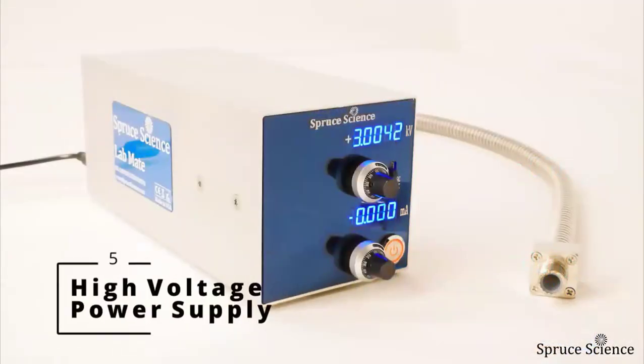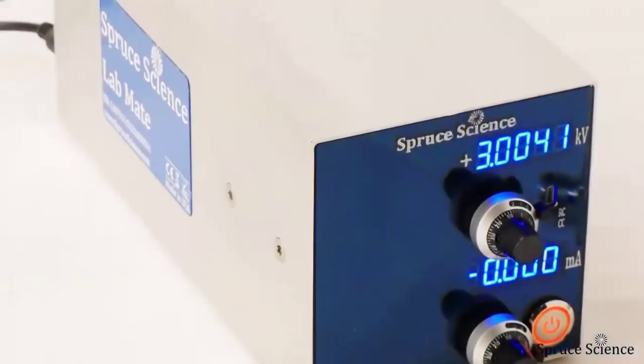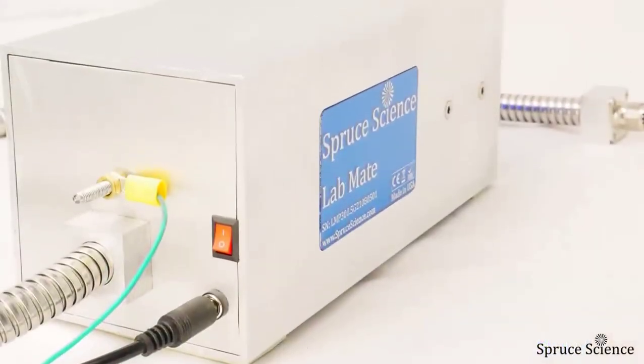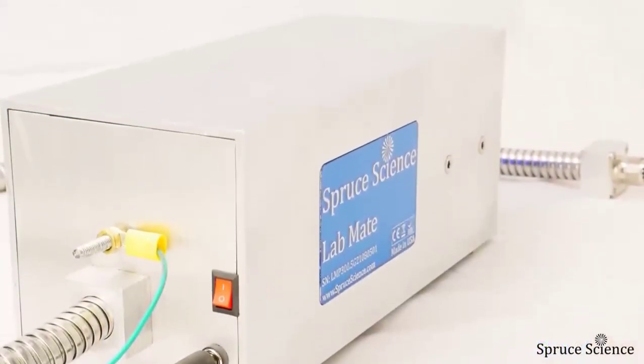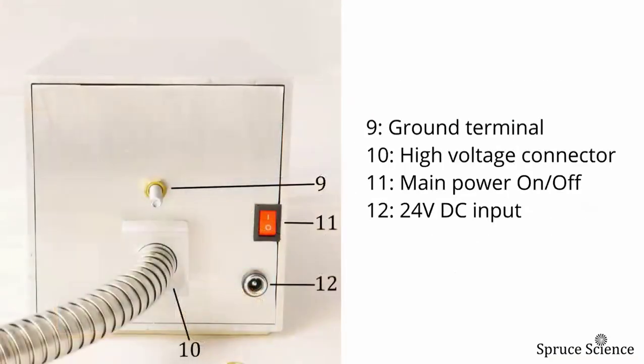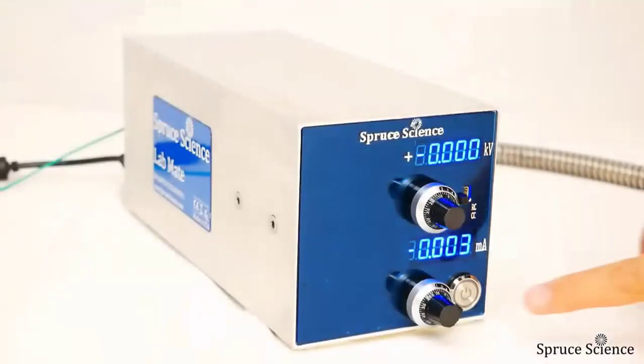The adjustable high-voltage power supply is a key component of the electrospinning setup, giving you complete control over the output. You can switch between constant voltage mode and constant current mode to suit your specific needs. This particular model can deliver a powerful 30 kilovolts, which is a great range for electrospinning applications. The current output limit is 400 microamps, which is more than sufficient for the electrospinning process and ensures that you have a good fit for your application.